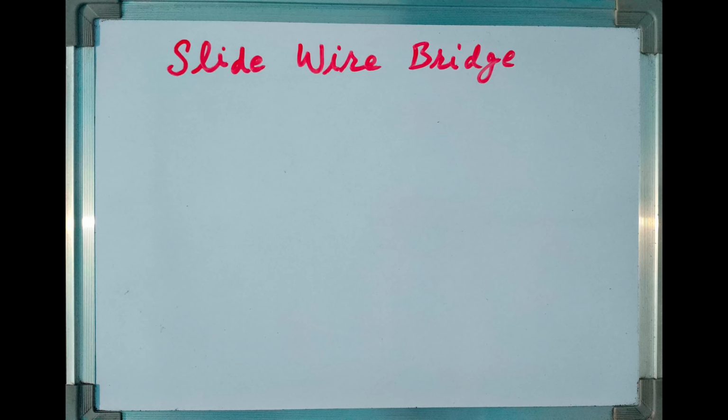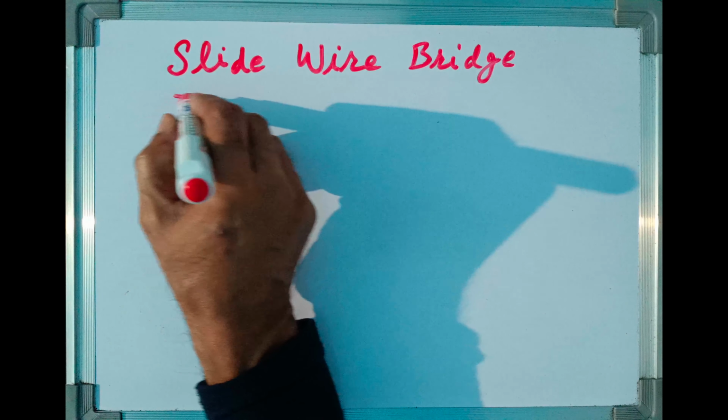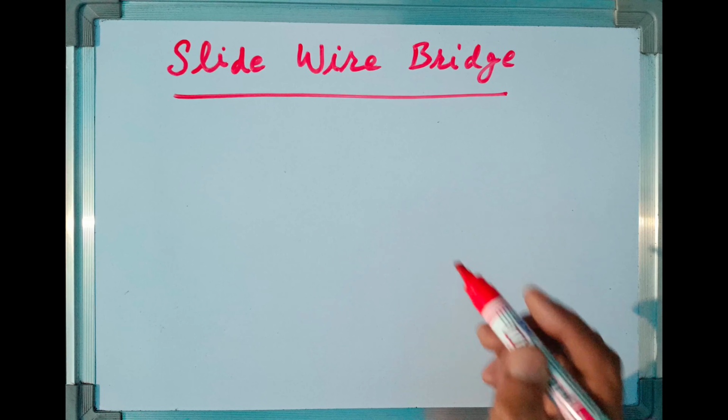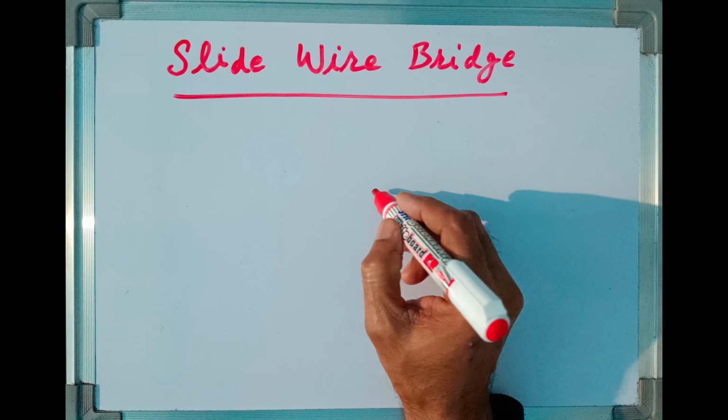In this video, I am going to share very important points about a circuit known as slide wire bridge. First of all, let us try to understand what is the construction of this bridge. In this case of bridge, we have a wooden board whose length is greater than 1 meter,